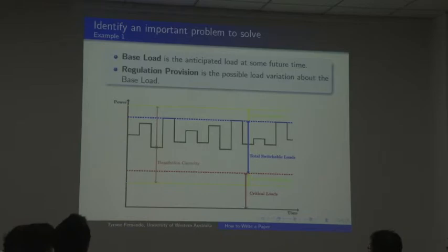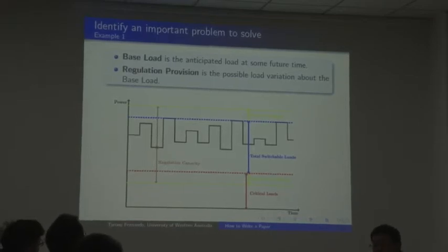Now, from the black line, if we turn on all the critical loads, the power requirement from the customer will be the blue dotted line, right? And if we decide to charge the battery, then the battery will act as a load, so the load will increase, and the power from the grid will be represented by the green dotted line, right?